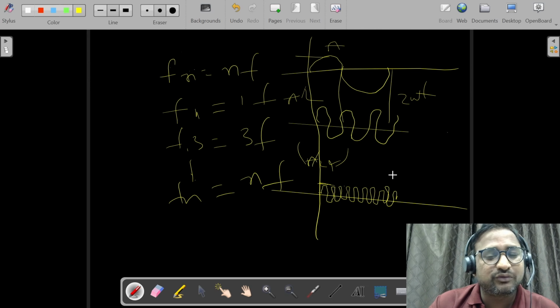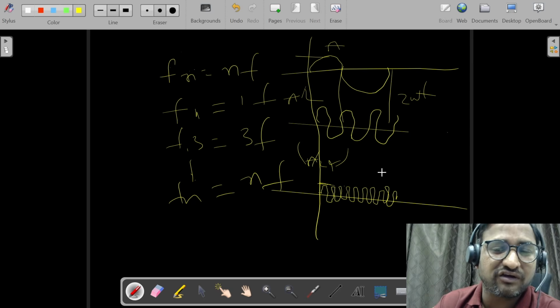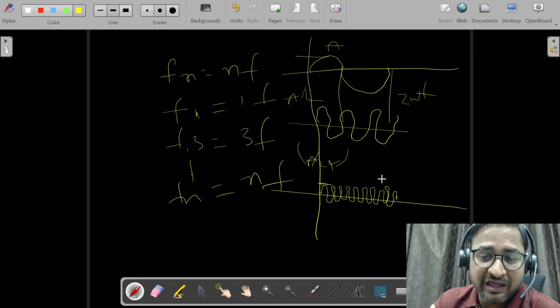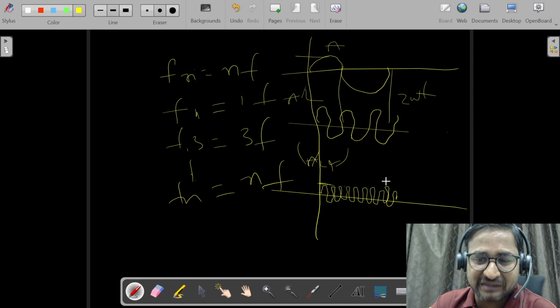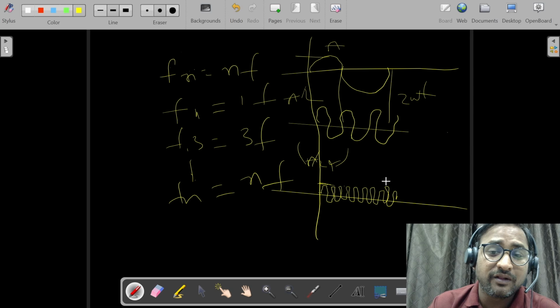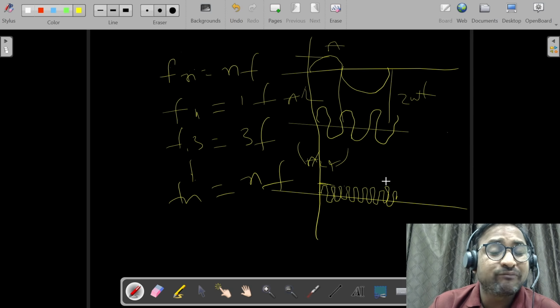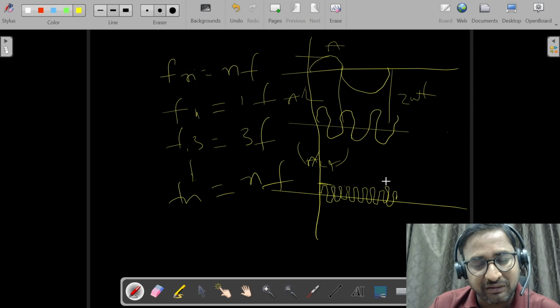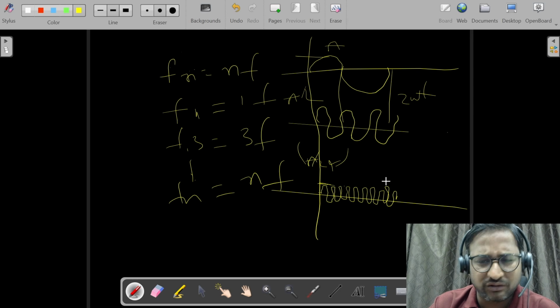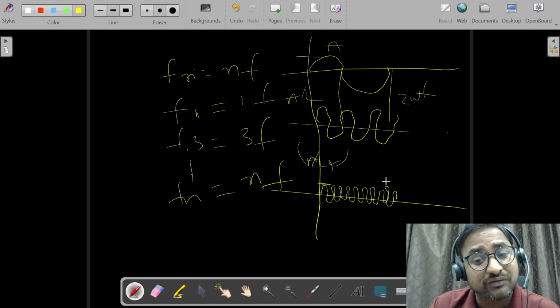This is the technique we use in electrical engineering, which I will explain in the mitigation of harmonics. There we basically use RLC filters, which are resistor, inductor, and capacitor. Those filters reduce the high frequencies. So finally, we use power electronics to reduce the low harmonics, and the high harmonics can be removed by a normal filter. In this way we can reduce the harmonics and give it to the system.